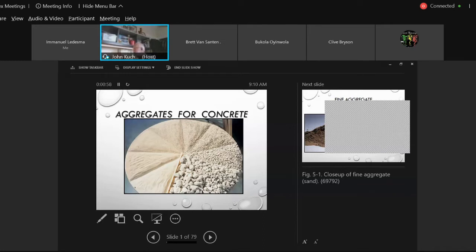Some of you may have worked with the City of Winnipeg and have tested the concrete that is being used in city projects. Well, those mix designs had to be made by the supplier, and then they had to get approved. So they look at their aggregates and they look at all their individual ingredients. So the City of Winnipeg specification, which is also uploaded into Lab 2, CW 3310 R17, that's their latest specification.